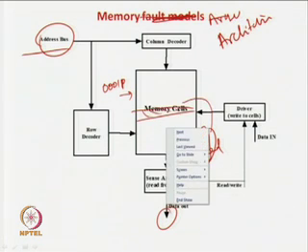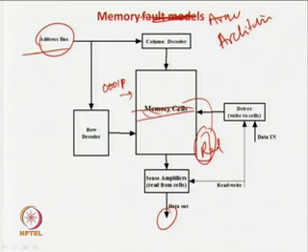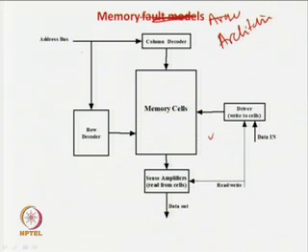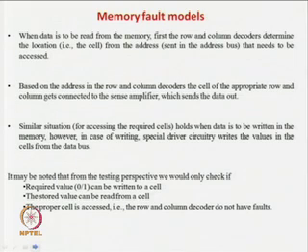This part was having some kind of problem, and this was a redundant cell. So this will not join here; it will come back here, and from here it will come back. So this is bypassed, and the new extra redundant cell comes into the picture. This is how it repairs after you detect some faults. This is a very broad outline of what the memory architecture is. As I already told you, whenever you have to read data from the memory, the row and column have to be selected accordingly.